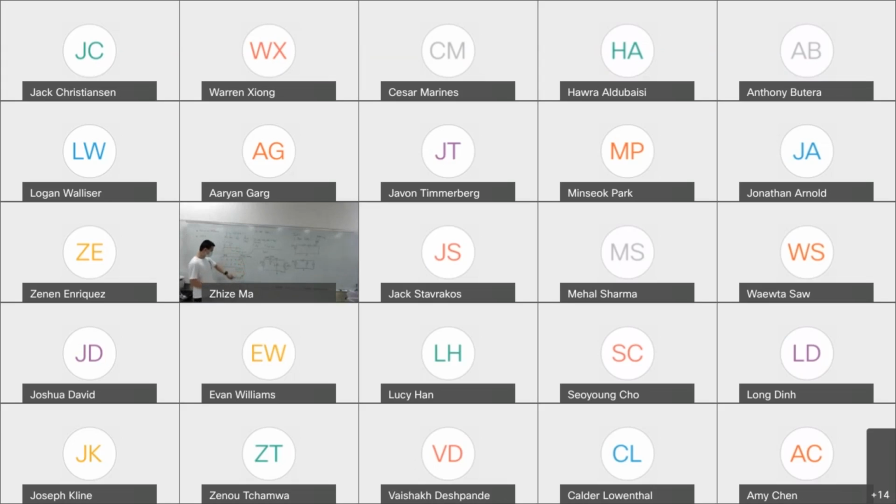For your DMM, I assume you already watched the tutorial video. There are 4 pins. 1 pin is common. This common should be connected to the ground of your AD2. When you measure voltage, you will use this pin. There's a pin for voltage and resistance, so that's the pin you will need.